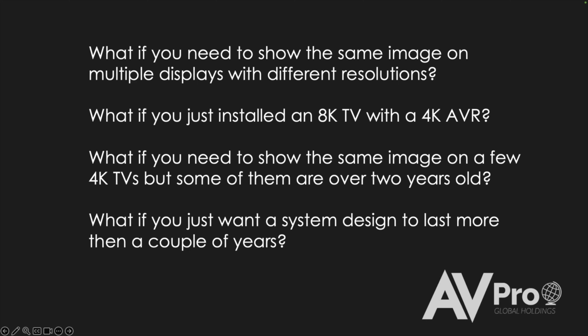What if you installed an 8K TV with a 4K AVR? In that particular instance, you might have 8K signals. You're not going to get audio through that AVR if it's an 8K or even a 4K signal with a 1080p AVR, because the AVR won't recognize the signal because it's over res. It was designed before that was a standard and before 4K or 8K was a possibility. So you're not going to get audio through it. The proper DA, which is what we're going to talk about today, will solve that problem.